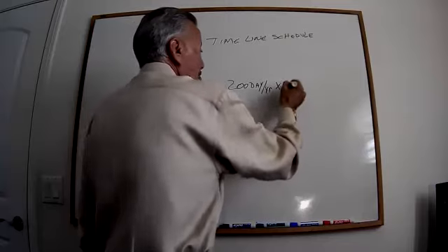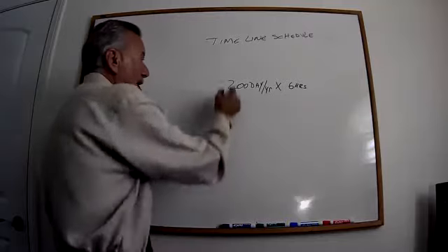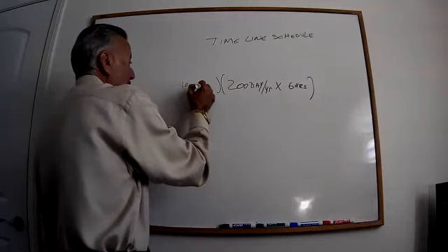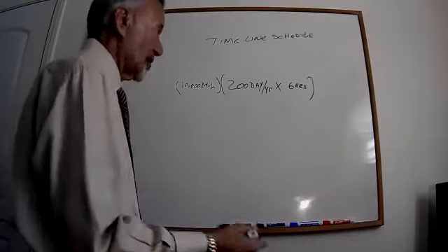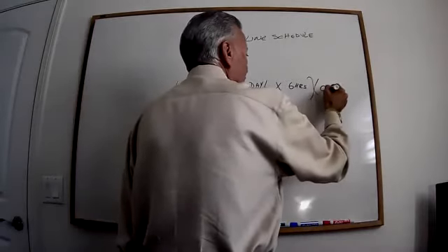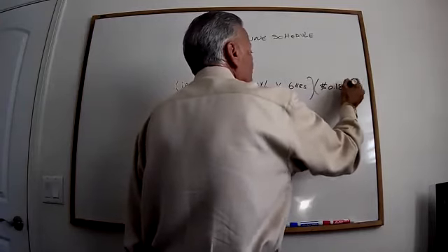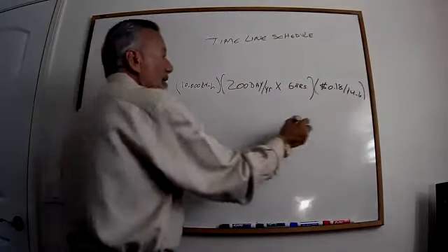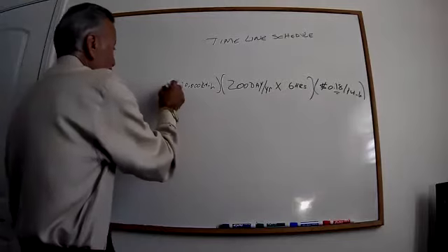And each day, I'm assuming I have 6 hours of sunshine, and I have 10,000 kilowatt-hours that I'm generating. Then I multiply that by the 18 cents per kilowatt-hour that I gave you, the rate at which you can sell your power. So this becomes your revenue.